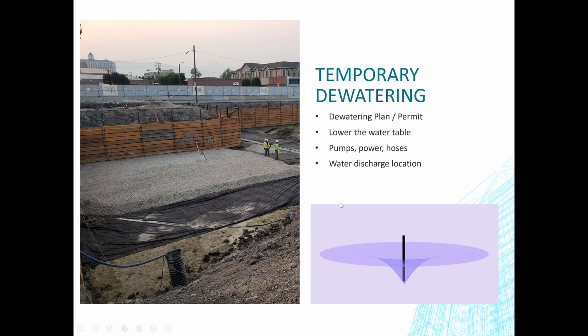Once they've dug this deep enough right here and say it's collecting water, it dewaters this entire area at an angle like you see in this picture. This angle here is coming off and maybe coming way over here. You can dewater large areas with just a single pit. Or if they did a trench along here or some other direction, it would look the same, other than instead of a single point, it would come off at an angle in a row.